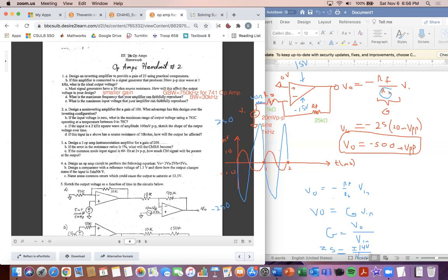And this input voltage is going to be 14 divided by 25 when you do it, and that would be plus or minus 0.56 volts. Oh, just finish that problem real quick. I'll ask after. Okay, so that's the max input voltage that your amplifier can faithfully reproduce.